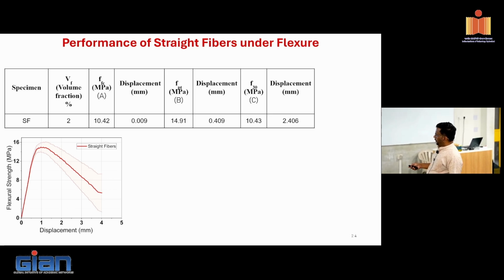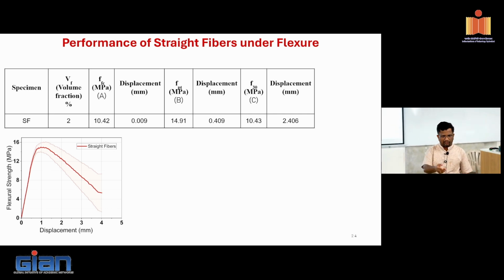This is for the same UHPC. I put in this brass coated fiber, the small fiber that I circulated. These are 0.12 millimeter in diameter and 13 mm in length. But these are the costly element in the UHPC. So now, can we replace these costly brass coated small steel fibers with normal steel fibers? Because again, from the Indian point of view, ours is a very, very cost sensitive market. If I want to promote this material, then I need to somehow optimize the cost of UHPC.